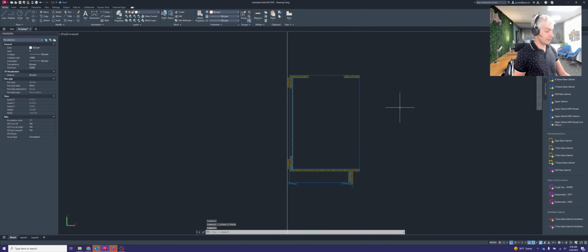The reason why that's important is because if you have an open cabinet or a tall cabinet, the customer is going to be able to see up into there as there is no door on that cabinet, or a tall cabinet, if the door's open, clearly you're going to be able to see up there because it's taller than a person typically. And so you want to make sure that you're not able to see the ceiling above, or in this case, if it's an open cabinet, you don't want to see the plywood subtop there. So that's only to do with open cabinets and tall cabinets. Any other cabinet, you can use the 2 rails that are here. So just worth noting at least.